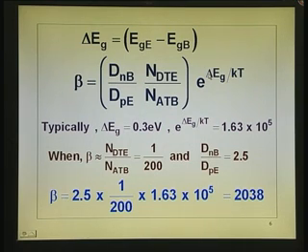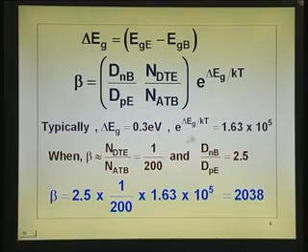Now you can see what you have bought by using an emitter which is not of gallium arsenide, but of aluminum gallium arsenide, with a base of gallium arsenide. So that is 10 to the power of 5. Now, I will choose Nd total 200 times smaller than Na in the base. I can choose 10 to the power 19 doping in the base and emitter doping 10 to the power 17. It looks very funny when you think of the homojunction transistor, but here it is a reality. Then you get a factor of 200.